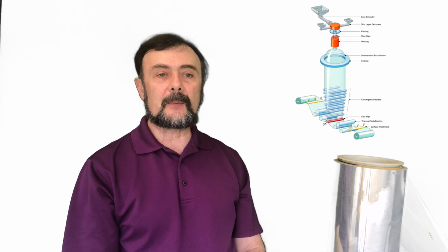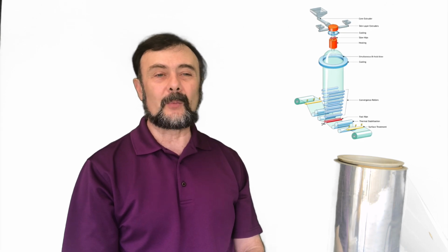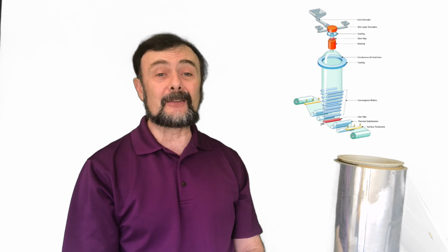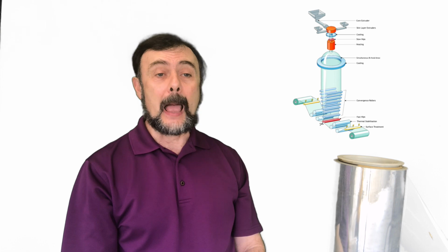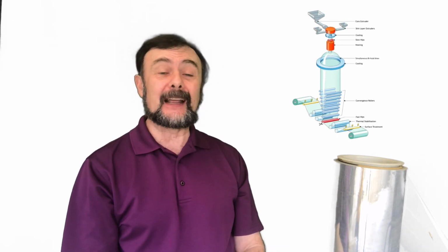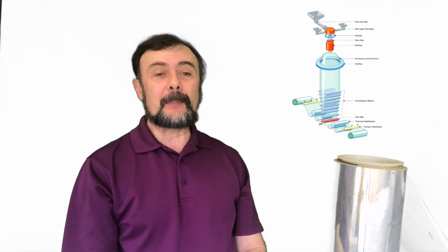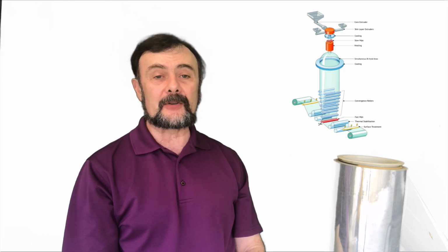When the brown speck made it to the infrared heating part, it would be heated more because it was dark and caused the bubble to pop. Well, actually, when a bubble is 5 foot diameter and about 50 foot long, it doesn't so much pop as it goes boom, and dust is shaken off the rafters, and everybody around knows it. It then takes 1 or 2 hours to get back to making good product, and in that 1 or 2 hours, you're making scrap and costing the company several $1,000s an hour.